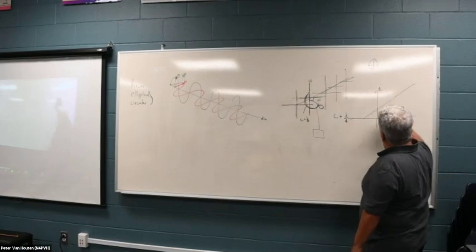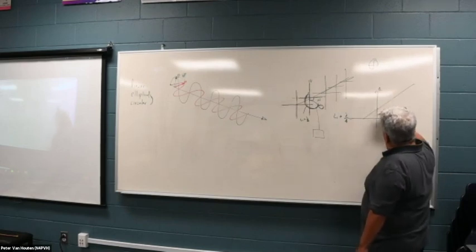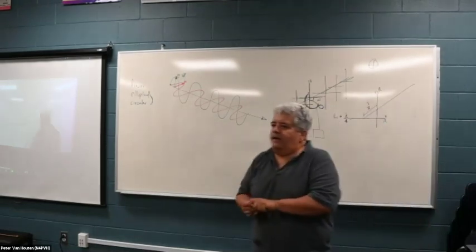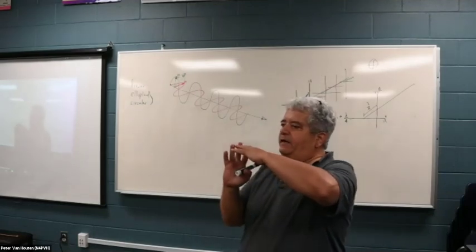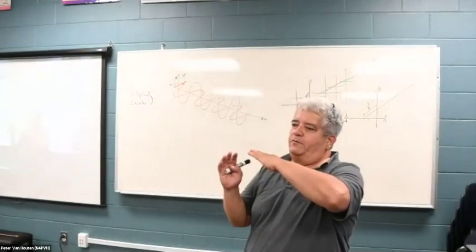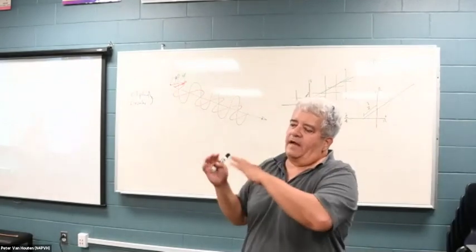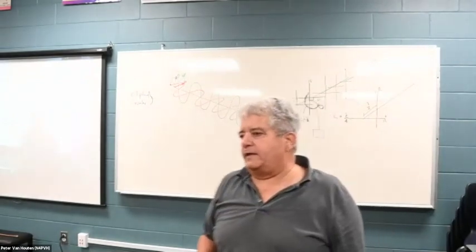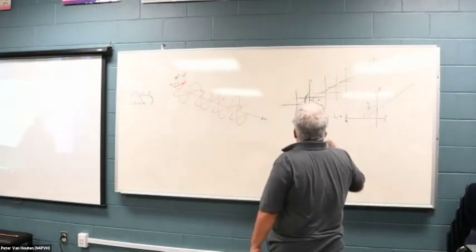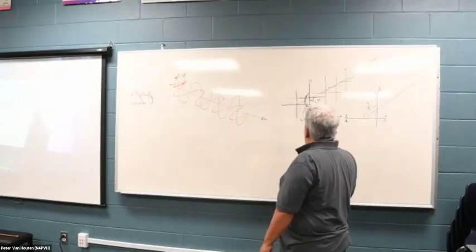This is vertical reflector, this is horizontal reflector. And then the distance here is going to be a quarter wave. So basically what I do is I build the antennas so that they have a difference of a quarter wave between the elements of the antenna. That's another way to get it. Okay, that's a way to get circular polarization.